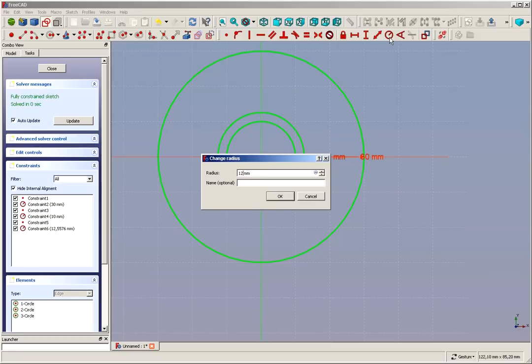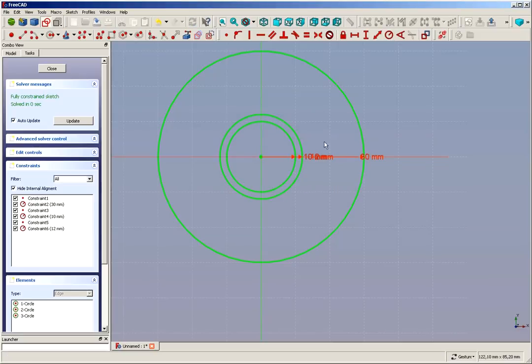And let's take 12 millimeters, so it gives us a bit more for the 3D print. We distribute our measures a little bit just to be clearer, and this is about all we need for our master sketch, which gives us our measurements that we're gonna need later on.